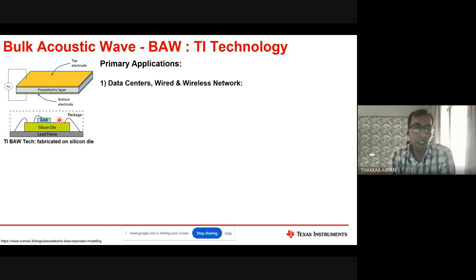So let's say, why did integrated ICs enable a lot of technology? Mobile phones and all were not so popular before we could do wafer level integration, because the circuits are the same. But if you take every MOSFET discrete and try to build a circuit, that is going to be a very big solution. So let's say you have a few amplifiers and some filters. Now, if you try to build it on a board, it's going to take a lot of area. And that's the reason mobile headsets or everything would become very bulky.